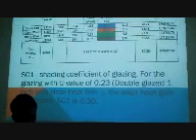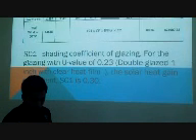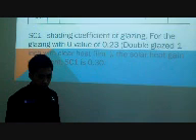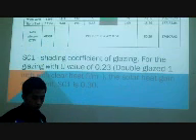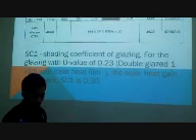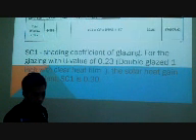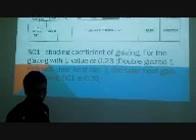Next we go to solar heat gain through walls. For this part, we have to find the shading coefficient SC, which equals shading coefficient 1 times shading coefficient 2. SC1 is the shading coefficient of glazing. For the glazing with U value of 0.23, the solar heat gain coefficient is 0.30. The next step is to find SC2.